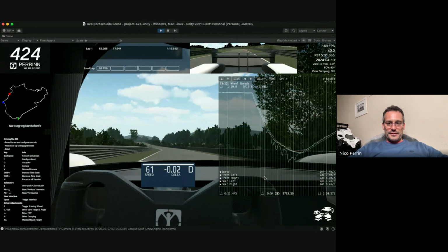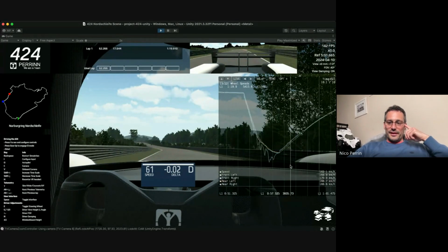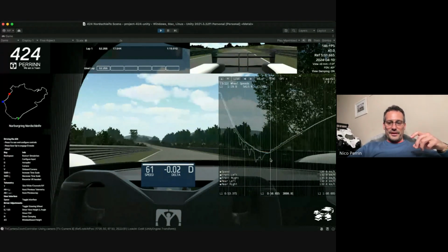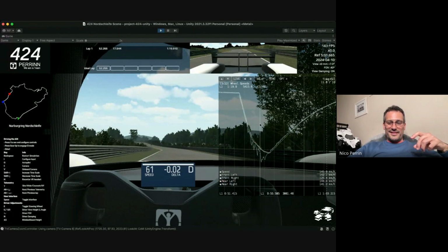And the wheel speeds, there's a little bit more sliding at the front than the rear, but there's more loading as well. But the wheel speeds are really following. And towards the end, the inside front will start locking, but it's not a huge amount. So I'm fairly happy with that. And look on exits, it's not like the front is oversliding more than the rear. So you can see, if you look at this, that's a fairly healthy picture, and we're pushing really hard here.